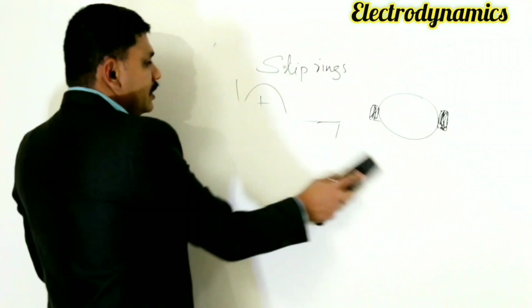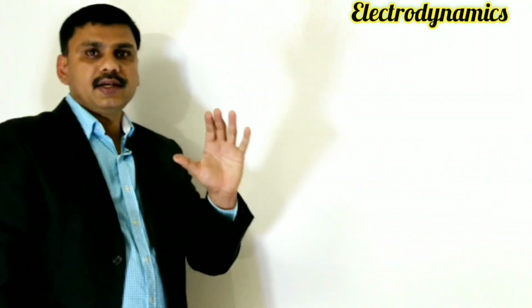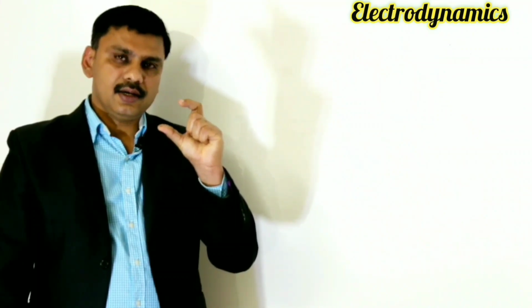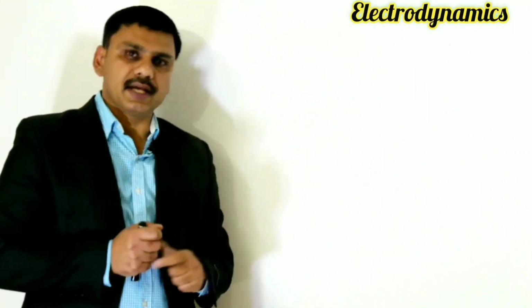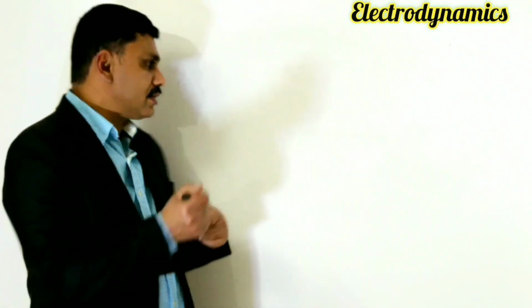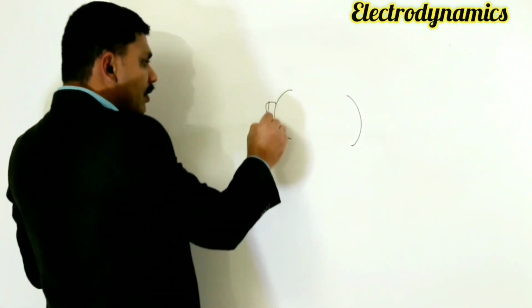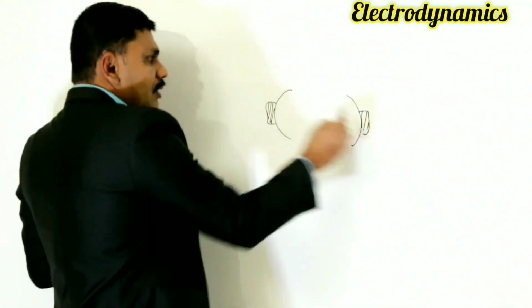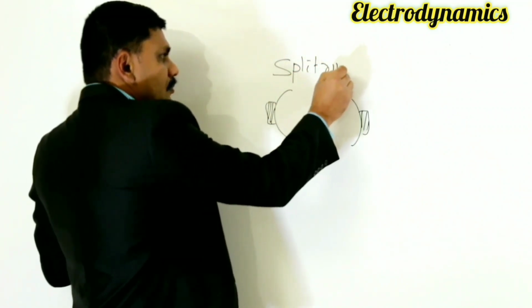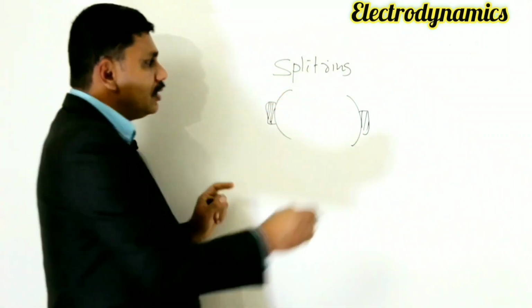So, AC generator and DC generator. From a diagram, how can you tell an AC generator from a DC generator? Check the generator. If it has slip rings, it is an AC generator. If split rings come like this, in contact with the carbon brushes, split rings like this, if the diagram comes like this, this is a DC generator.